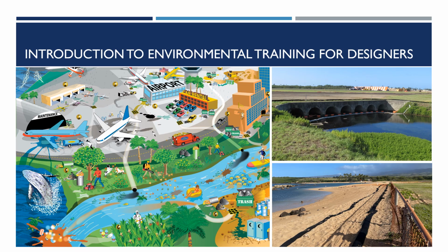Stormwater runoff can pick up harmful pollutants and deposit them into drainage systems, streams, and the ocean. Construction activities may be sources of potential pollutants such as sediment, concrete waste, vehicle and equipment fluids, material and chemical spills, lavatory waste, and trash. Stormwater is typically not treated after reaching the storm drainage system, which means pollutants could have the potential to reach our streams and oceans. On-site pollutants can also contaminate the soil and groundwater.